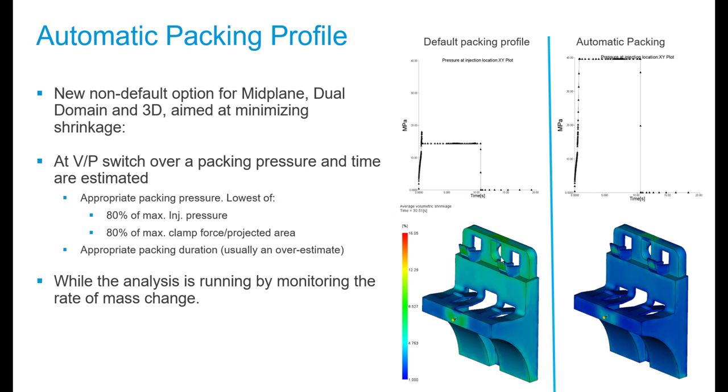Another big improvement, and this is a non-default option for Moldflow Insight, and Advisor is going to have the same ability, by the way, is the automatic packing profile. It's not a default.